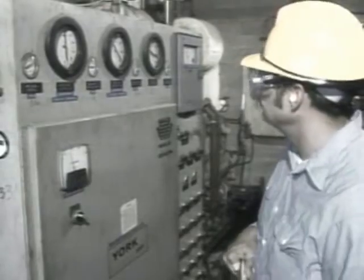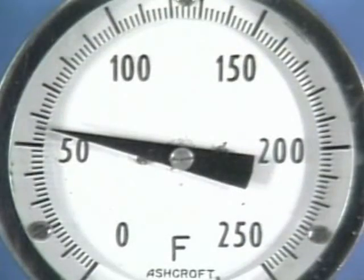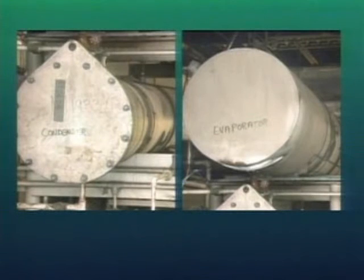Operators routinely check the temperature indicators associated with a refrigeration system. In most cases, there are temperature indicators for the substance being cooled and for the discharge of the compressor. The condenser and the evaporator may also have temperature indicators located on their inlets and outlets. These indicators can be checked to see if heat transfer is taking place properly.